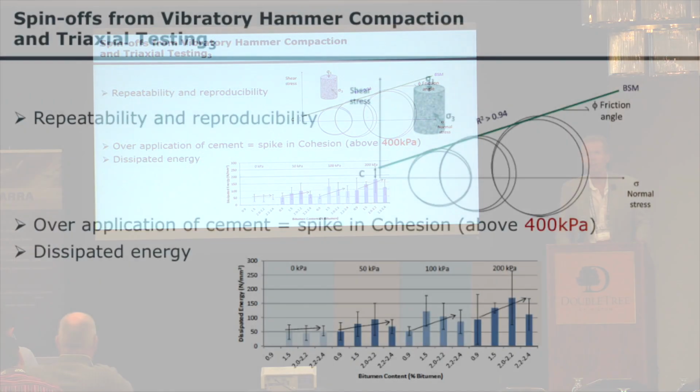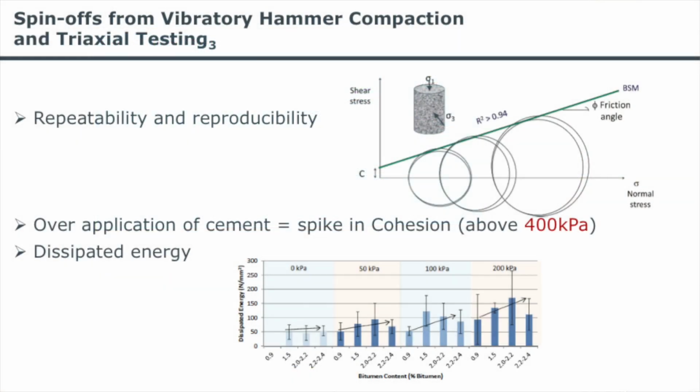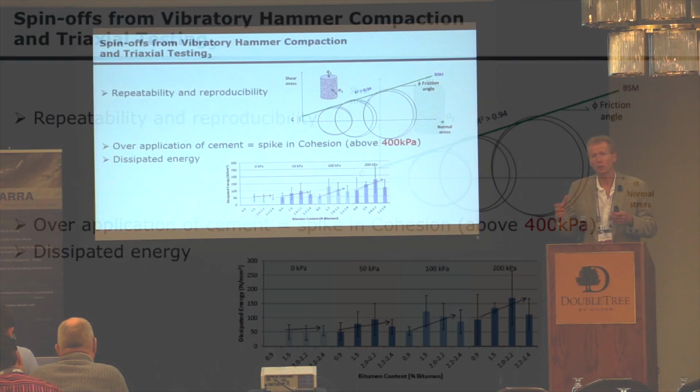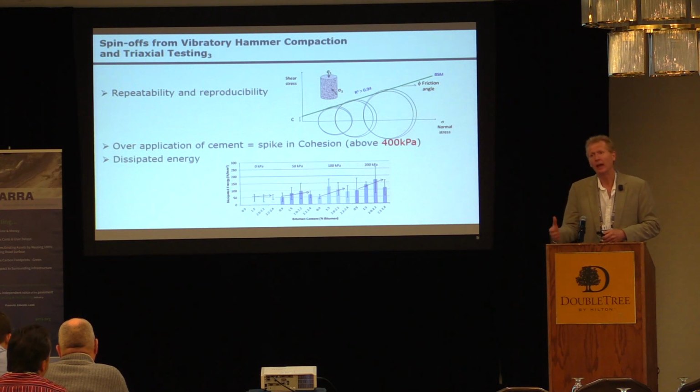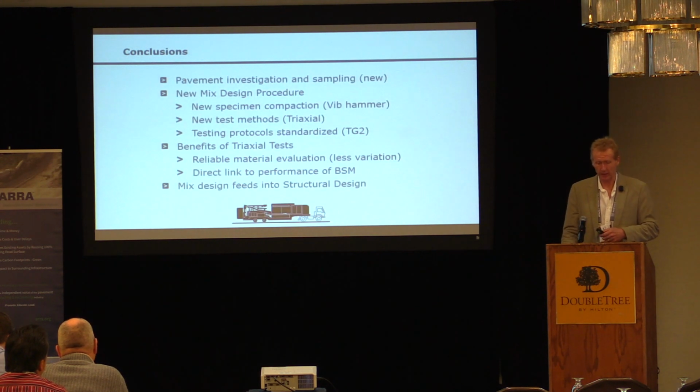And then on that dissipated energy consideration, our research has shown what the key variables are that we need to consider. Confinement, moisture is another one. Confinement also is enhanced through compaction, so in your layer you can create more confinement by getting a better compaction. And in order to do that, one thing that's necessary is having the right grading, so you have the right packing.